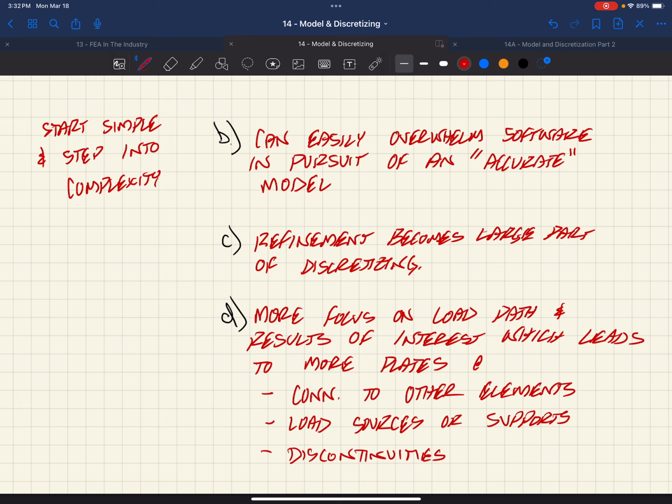So there's this idea of, well, if we're going to have this applied load, do we spread it out over multiple nodes, right? And maybe we create 100 elements that represent the boundary of a base plate of a column that's deciding that it wants to land on our floor, right? And then we apply a pressure onto those plates instead of discrete point loads at the nodes of those plates, right? All of those things are going to help us to distribute that load prior to now having to distribute it throughout our elements, right? Because otherwise we're going to get these huge spikes, and we'll see it later on when we start modeling plate elements.